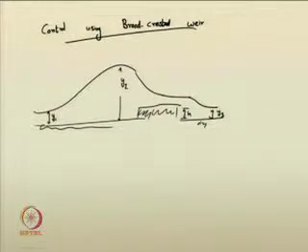So, for these following conditions, one of the situations is how the broad crested weir acts as a control. One thing you have to remember is that the minimum possible flow, or the type of flow that can be possible over the weir, should be at least critical, right.